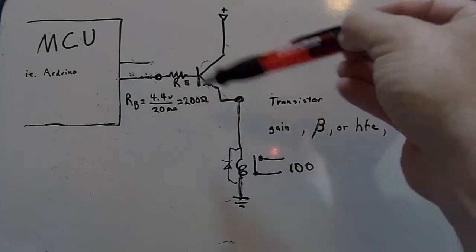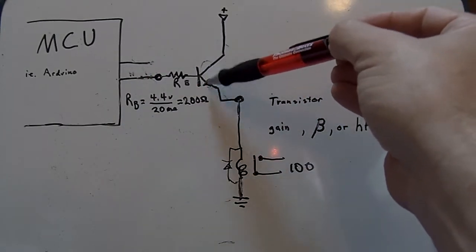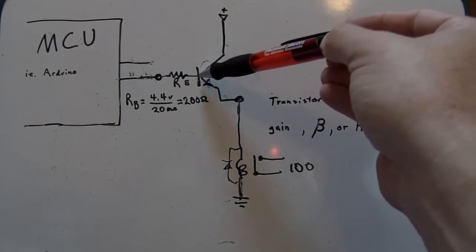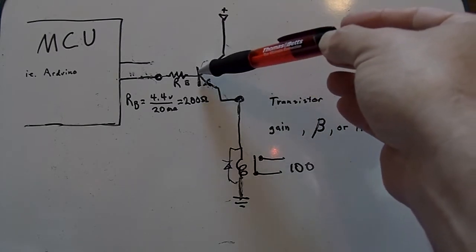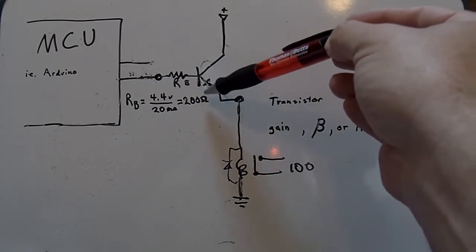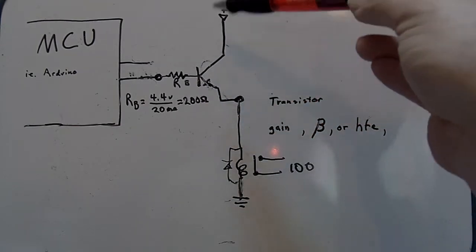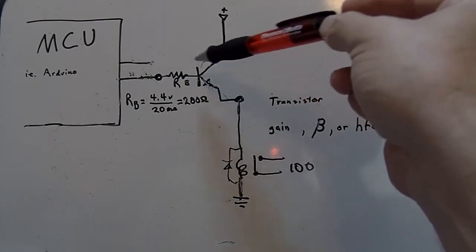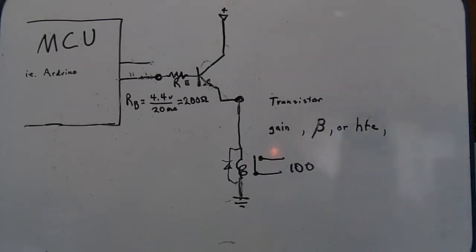So I don't have that inversion I had with the last example, using the PNP and the emitter up here instead of down here. But again, your output should normally be off your collector, and your input signal should go through with as little weirdness as it can. That's why the circuit fails. You're taking the output off the emitter, and you're also making the bias current see this funny load. So this is a less optimal way of doing things.